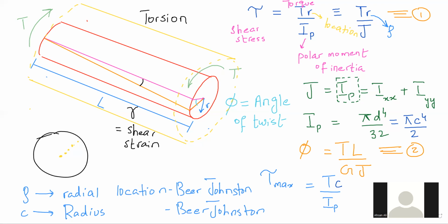It's more like if I am pulling this and if I ask you, give me the normal stress on this section, what you will do is you will cut it and you will throw this chunk away. You will put a reaction, and let's say I'm pulling it with 5 Newton. On this section, you will put 5 Newton. On one section, there is one force. Similarly, if you're twisting, when you slice it on one section that I'm seeing, the circular chunk, I'm just seeing one torque on it. It's just that one torque on different points on that section is giving me different shear stresses. That depends on the location, the diameter and stuff like that.